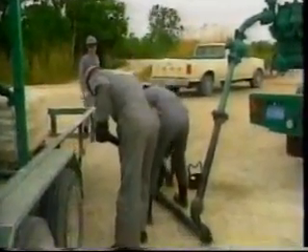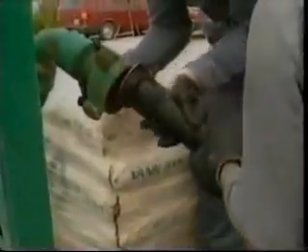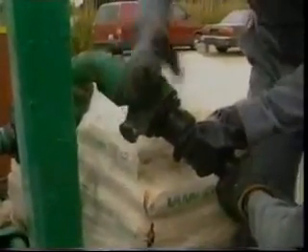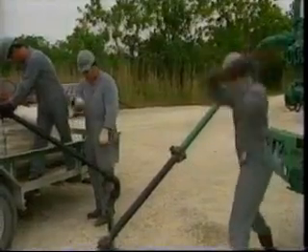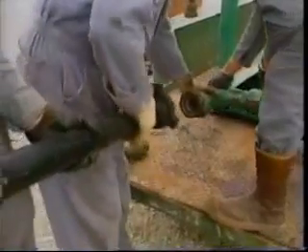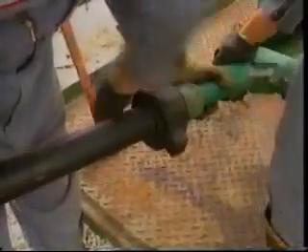The formation composition analysis has shown that the sandstone formation has less than 10% HCl soluble components, so an HCl-HF acid seems appropriate. The pressure transient analysis of the buildup data from the subject well shows that a skin factor of 8.0 is severely limiting production. The skin damage is believed to be caused by the kill fluid used when artificial lift was installed. Because the damage is probably shallow, acid penetration of several inches should be enough to restore well productivity.